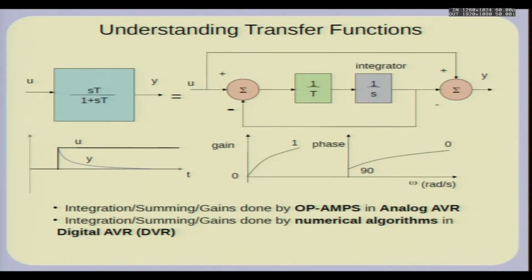I have just done it very approximately. You can try using simple tools to plot this on a log scale and see the response, and you will find that it has a gain of 0 in steady state at very low frequencies and 1 at high frequency. Of course, although I said log scale, the 0 and 1 are not in log. What I have shown here, 1 is actually before you take the logarithm. So, in a log scale, do plot it and you will find at low frequencies the gain is 0, or in the log scale it will be minus infinity.